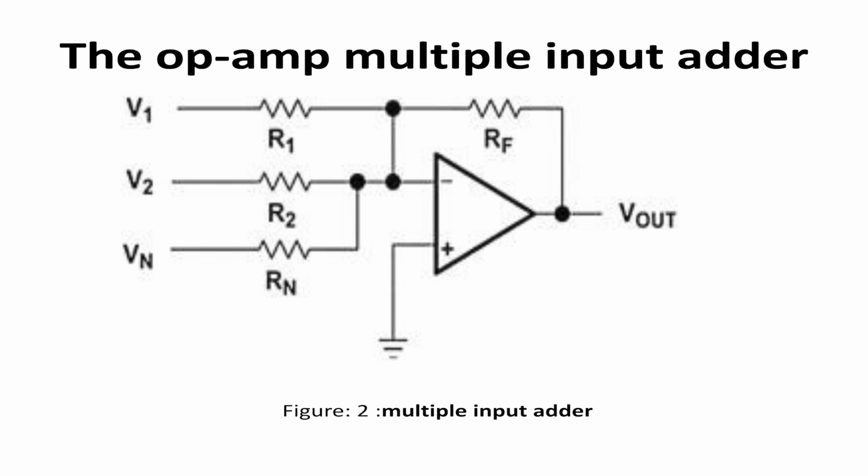It was discussed earlier in this topic. Once again, I will just clarify this. If you do not want inversion, you can remove the negative sign, resulting in a non-inverting op-amp adder circuit. The gain of each input voltage V1, V2 is determined by the ratio of the feedback resistor Rf to the corresponding input resistor R1, R2.